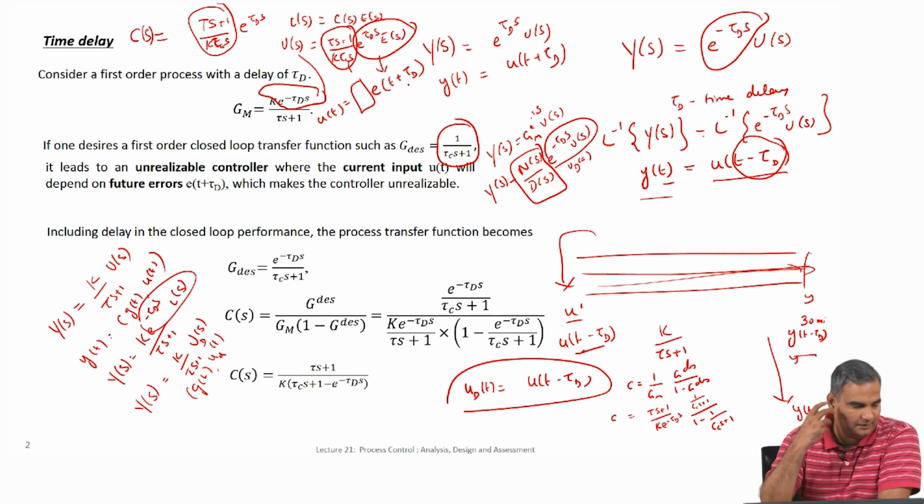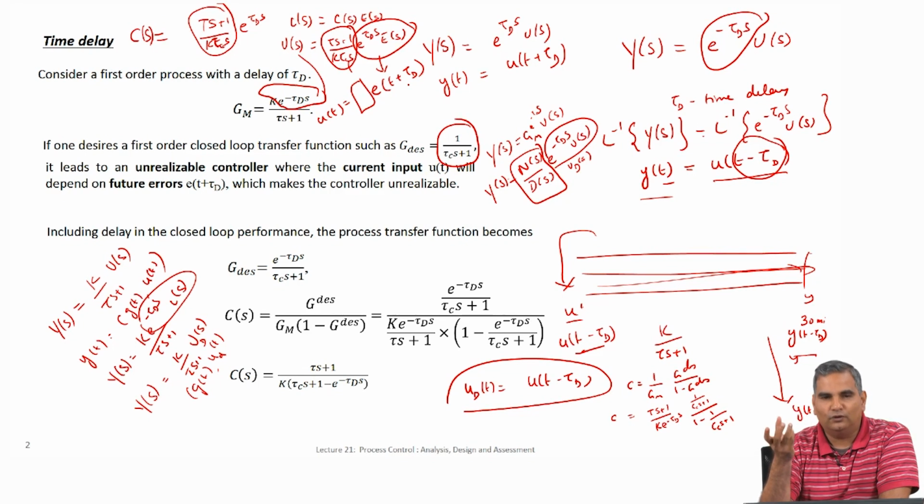so that introduces a delay. But typically what happens is when you open the knob for the hot and cold, the mind says, okay, hot water has to come in, but hot water is not coming in. So the first thought that comes is really not time delay, it is that maybe I have not opened the knob enough, so the flow of hot water is much lower than the cold water, so that is the reason why the water is still cold. So you will increase the knob, then more flow is there, but still hot water is not coming in. But ultimately, if you open the knob too much, when the hot water comes in, it is going to be scalding hot, right. This is something that many of us might have felt at some time or the other.